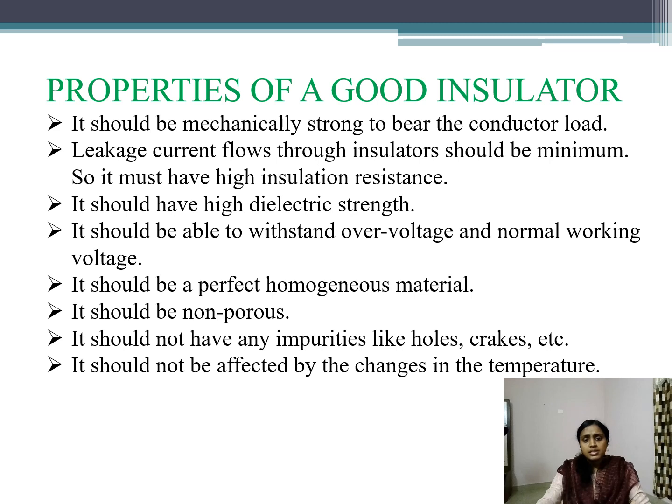So now we'll discuss about properties of a good insulator. A good insulator should be mechanically strong to bear the conductor load. Leakage current flows through insulator should be minimum so that it must have high insulation resistance. Next, it should have high dielectric strength. It should be able to withstand over voltage and normal working voltage.